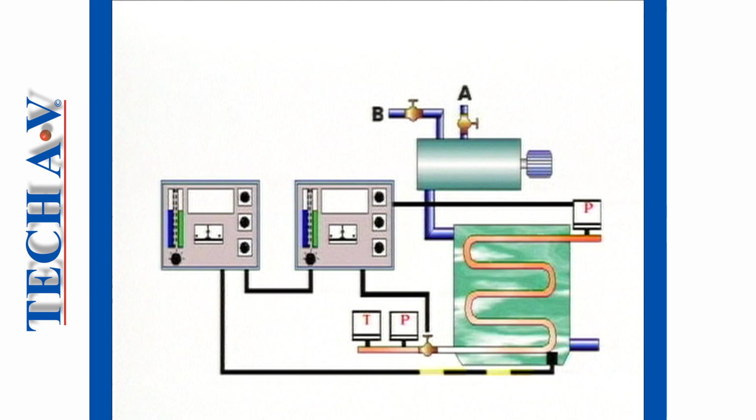The outer, or primary loop, still responds to variations in product temperature, but instead of positioning the steam valve, its output is used to adjust the set point of the secondary controller. The secondary controller then repositions the valve whenever its set point is altered.